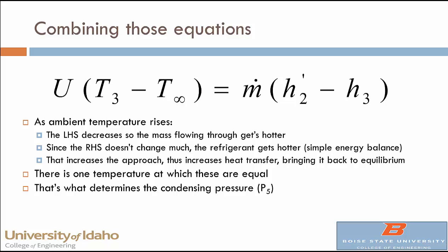So if you push one of these, something else is going to push back, right? It'll find an equilibrium. So in any given condition, there's really one temperature of the condenser that makes it work, right? And it needs to establish itself. We can't just set that.